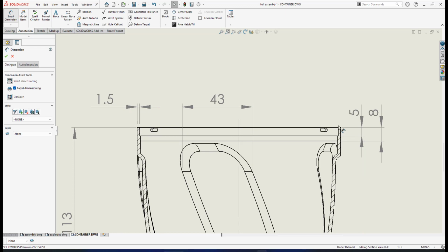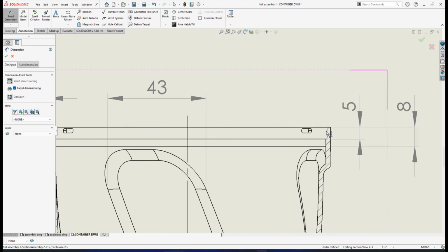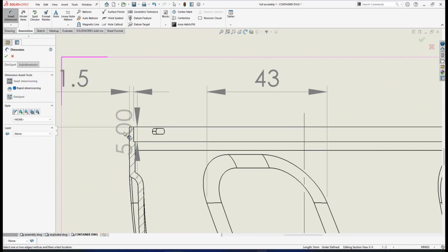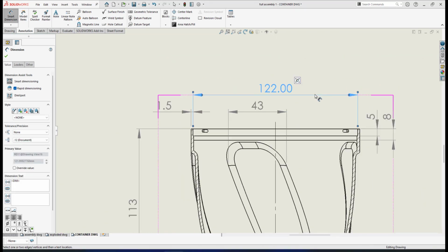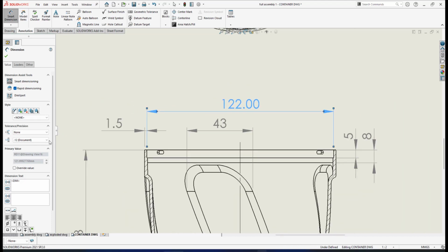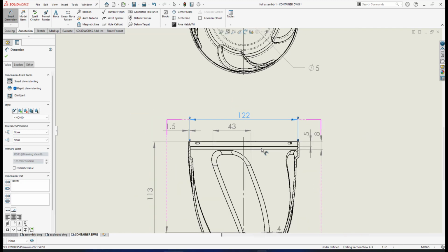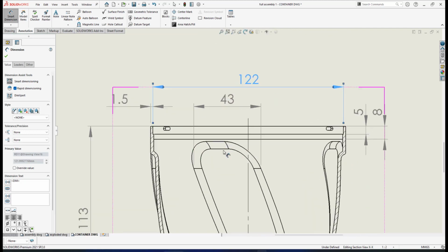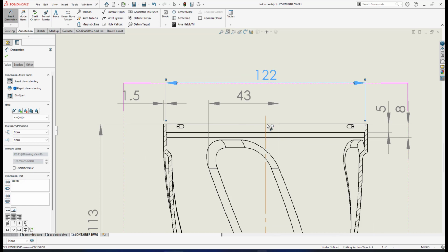I put dimension for this part, and hold on, and this part. I click at that, and I go for the icon. I put the upper parts. As you can see, SolidWorks automatically puts the second level. The distance between this dimension line is 3 millimeter, 1 letter height. So this one I go for not the decimal point, so 1 to 2. All right.